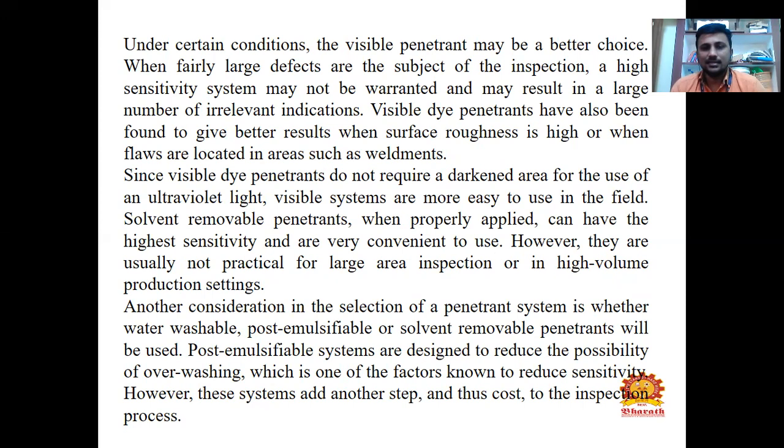Another consideration in the selection of a penetrant system is whether the water washable, post-emulsifiable, or solvent removal penetrant will be used. The post-emulsified systems are designed to reduce the possibility of overwashing, which is one of the factors known to reduce sensitivity. However, the system adds another step and thus cost to the inspection process.